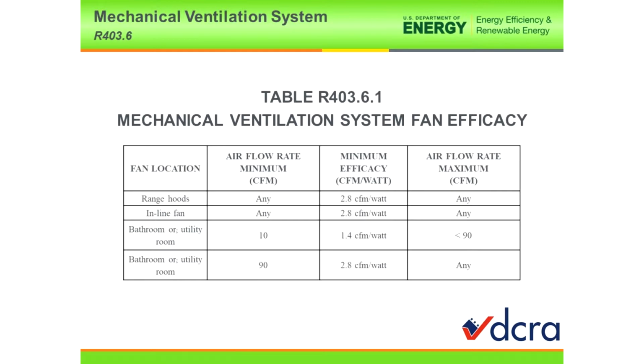That's how efficacy is calculated, okay? Or give us a spec sheet and supporting docs that shows that your fan is an Energy Star fan, okay? Then you're good to go. Other than that, you're going to have to show us CFM and wattage data on your fan schedule so we can calculate compliance, okay?